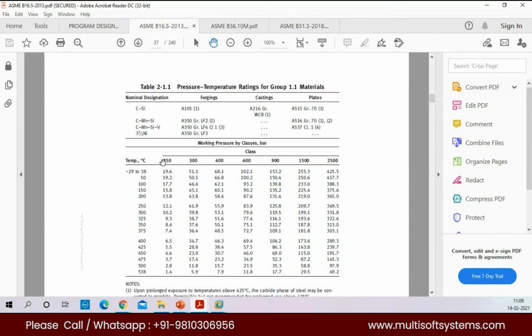But from my understanding, we can't take only the pipe material, the flange material, the elbows; everything we have to take care of. For the process also, we have to consider what the fluid is. If it's a highly corrosive fluid, even for lower temperature, even for 80 degrees Celsius, we can go for stainless steel material. There is no criteria that up to 427 we have to go for carbon steel. Not like that. If it's a highly corrosive material, then we can go for stainless steel.